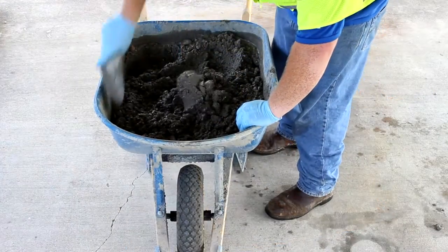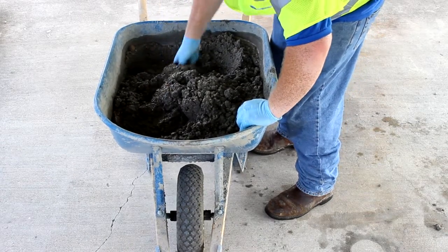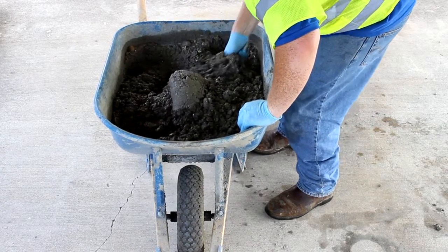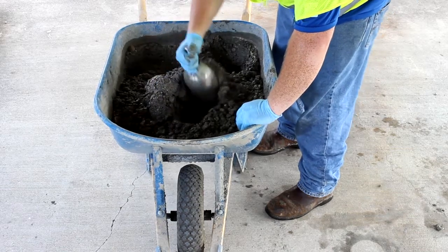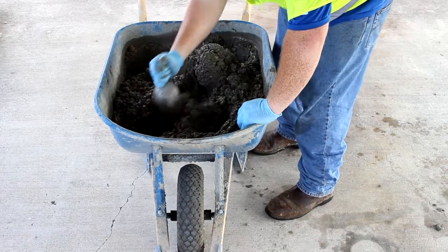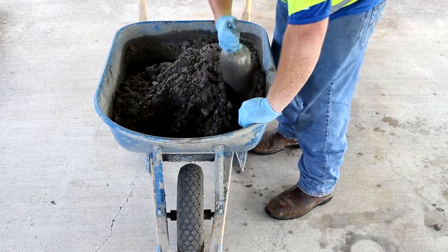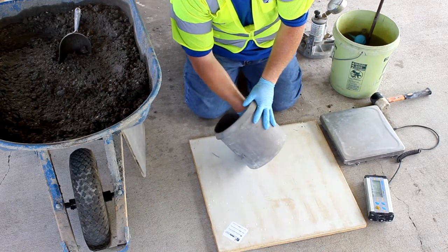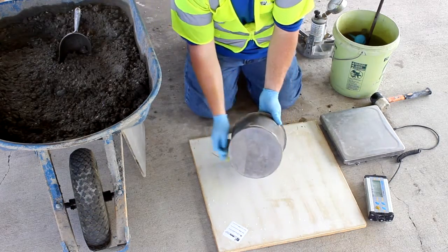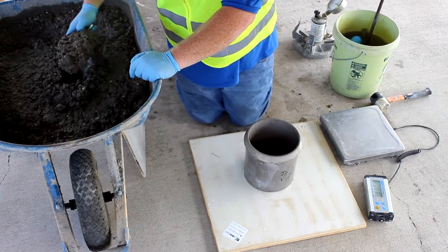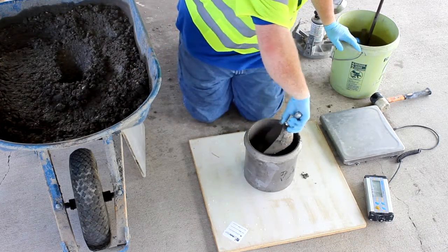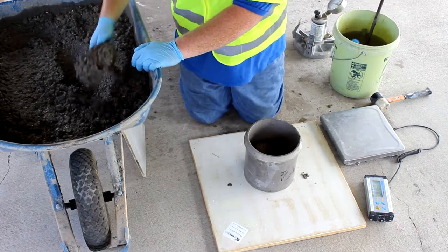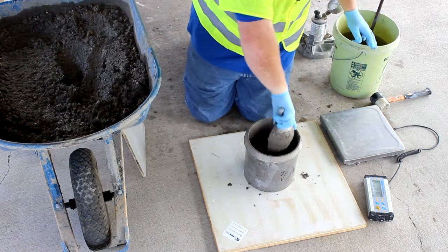This test method is applicable to plastic concrete. If the concrete contains coarse aggregate particles that would be retained on a 2-inch sieve, wet sieve a representative sample over a 1 1/2 inch sieve. Dampen the interior of the measure and place it on a flat, level, and firm surface. Remove any standing water from the bottom of the measure. Fill the mold in 3 equal lifts. Rod each lift 25 times uniformly over the cross section with the rounded end of the rod.